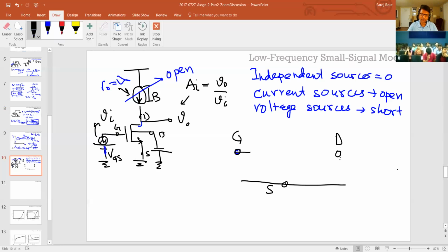It is sort of a multipolar system. In other words, you can make the drain as common node, gate as common node, source as common node, doesn't matter, as long as you have all the elements from each of the terminals, okay? So the small signal voltage VI here appears across gate to source. So I apply that VI, gate to source, and that's your small signal VGS as well.